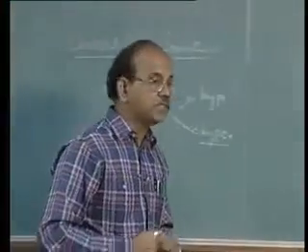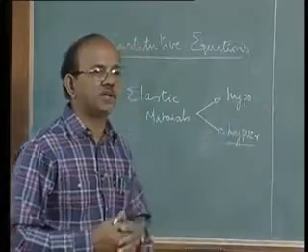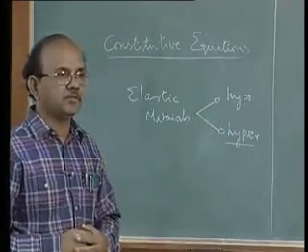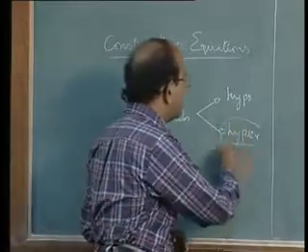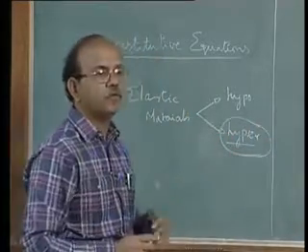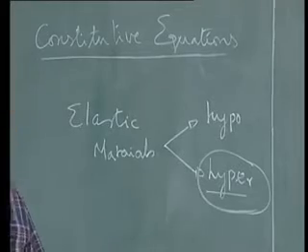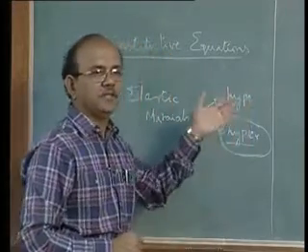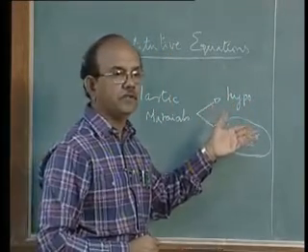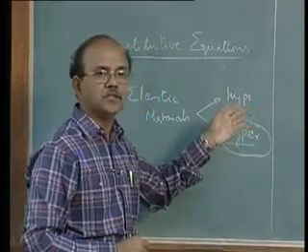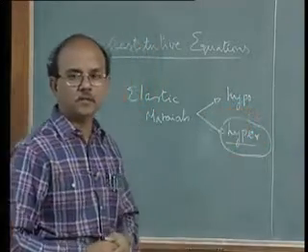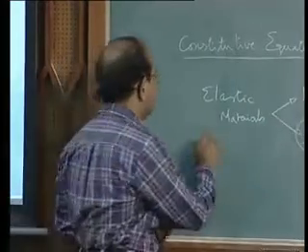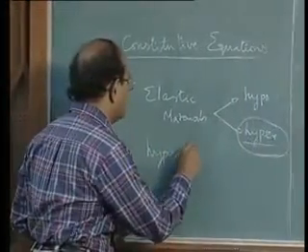But since the approach of hypoelasticity is not that very sound, in fact purists do not agree with hypoelastic material, most of us look at only hyperelastic materials for further analysis. Right. So we will abandon the hypoelastic theory for the time being. I shouldn't say that everyone has abandoned it. There are situations where people use hypoelastic theory. But let us now proceed in this course with hyperelastic theory or hyperelasticity.